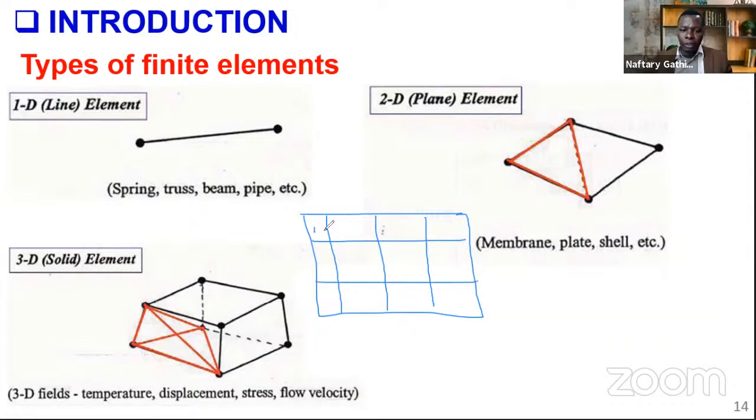Okay. So this is element 1, another element 2, another element 3. This element has got 4 nodes. Okay, 1 node there, another node there, another node there, another node there. Now we extract this individual element. This is the one that we have given here in this figure. Now in each of the nodes, remember we have ignored the thickness direction. We assume it's negligible. So we have this axis, the Y, and the X direction.